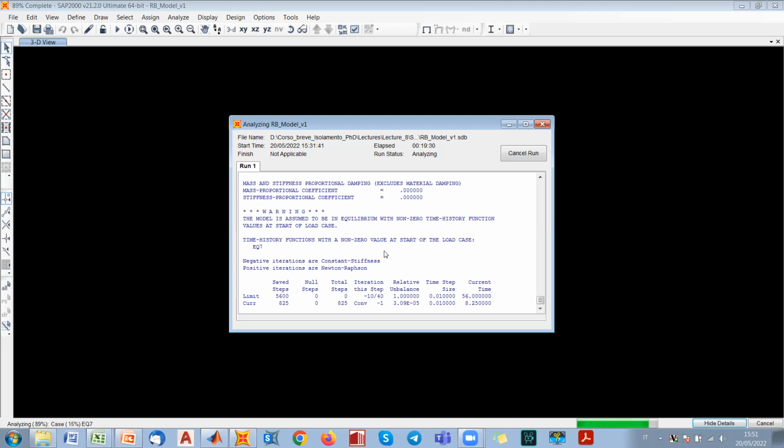Yeah, you're welcome. Generally, when there are no specific rules or quantitative values regarding some parameters, standard codes just say that the structural engineer has to define them. So maybe it is just upon the decision of the structural engineer. And we have seen that the superstructure also plays a very good role within the recentering capability. So maybe we get close to zero in all cases, but the higher the nonlinearity of the system, the higher could be the residual displacement at the end of a seismic event.